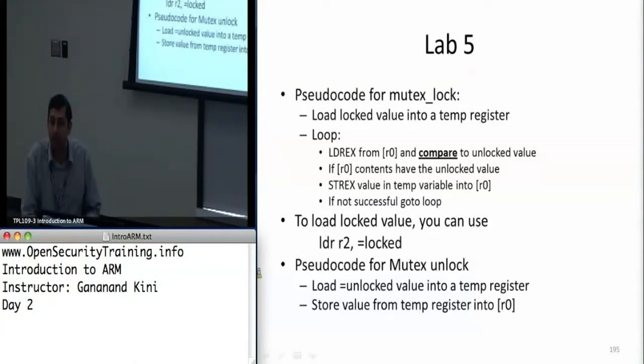And with virtual memory implementations on some of the SoC boards, it will actually mark the physical address, and the VMSA implementation has to take that into account, essentially. But those two are a pair, which means if you use LDREX, you can't use STREXB. You have to use LDREXB with STREXB and LDREX with STREX. Does that make sense?